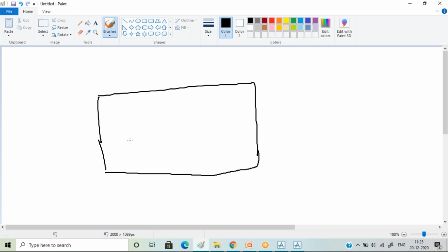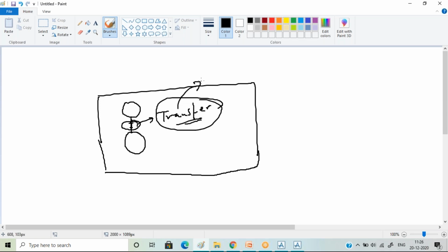If there are two equipments over here, I've seen a lot of plot plans and equipment layouts where people are not considering the small niggly things, but they play a very important role. Say if you have fixed two equipments facing each other, and there's a direct connection from this pipe to this pipe, and it starts behaving like a transfer line connection, this is a big problem. Again, this line has to go into stress analysis. So your equipment has to be placed in such a manner that your piping is the minimum and your stress is also the minimum.